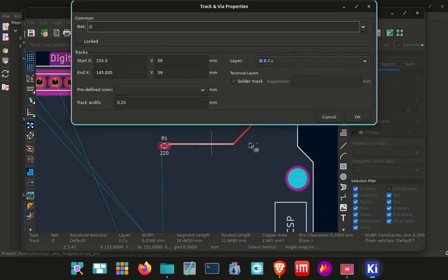BCU is behind the board, the back copper face. Now I use back copper face and I stick the components on the front when I make a board. That's absolutely fine, but whichever way works for you. If you need to swap tracks, you don't need to redesign the board in reverse. You just change whether it's on the front side or the back side.